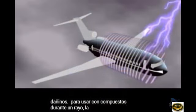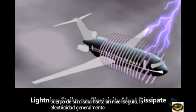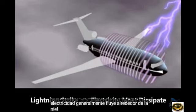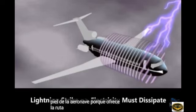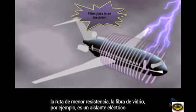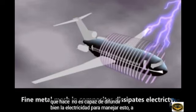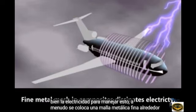During a lightning strike, the aircraft needs to dissipate the energy around the body of itself to a safe level. Electricity generally flows around the skin of the aircraft because it offers the path of least resistance. Fiberglass, for example, is an electrical insulator, which makes it not able to diffuse electricity well. To handle this, a fine metal mesh is often placed around the outside of an aircraft.